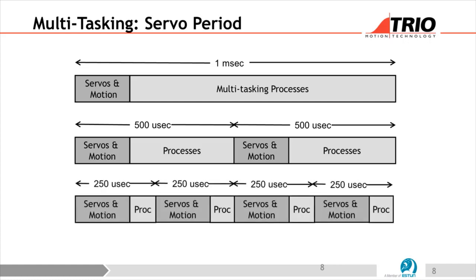Now, if I go to 250, look, it really gets much worse. So when we get customers who say, oh, I must close my loop at some crazy fast rate, you say, okay, fine, you can do that, but don't expect peak performance on all the other stuff, because it is going to affect it. Yeah. And there are not many real systems where you need to get down to this level. I mean, you're talking about lifting masses on, or people on hoists. Milliseconds, fast enough. They're not going to go very far in a millisecond. Their inertia.